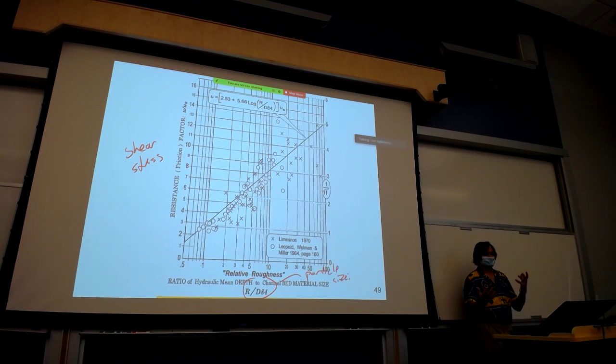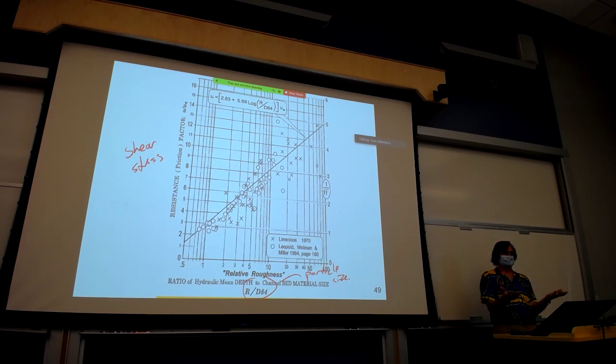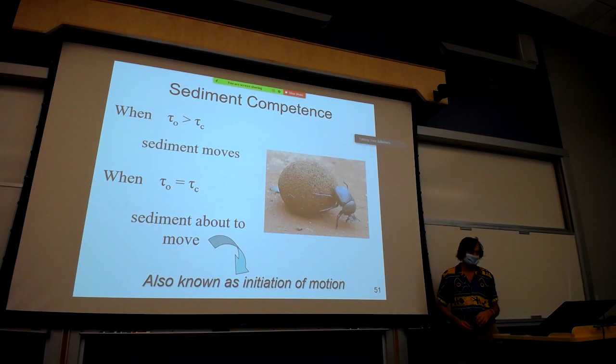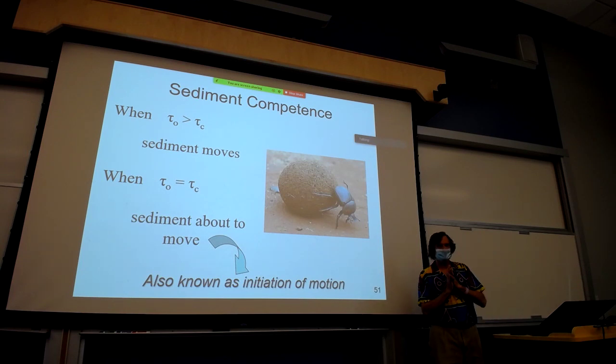And these are actually what we use when we're looking at designing sediments. So let's say you wanted to design a riprap swale. You need to figure out which particle is going to be resisting the stream shear stress. So again, you can look through all of those. That's all spinach for the mind. I just threw that in there for you. Questions?